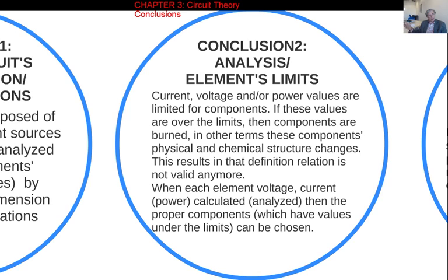Once you see these output signals as you expected, that means your circuit is working. Why are we calculating the other elements, current and voltages? That is the answer. Once you find all the elements' current and voltages, then you can check the calculation results against the elements' limits.